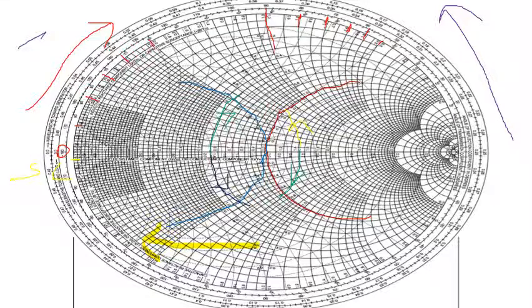So your readings will start somewhat from here. You will start at 0 here. This will be your 0.1, this will be your 0.2, 0.3, 0.4. Can you all see it? It's dotted. So the same line can be used as an arc of solid as well as dotted. When you take the reading of a dotted arc, the reading goes on increasing from the opposite direction. It will move in the anti-clockwise direction, which I have shown in purple over here. When you take a solid arc of impedances, the reading goes in the clockwise direction from the left hand side.